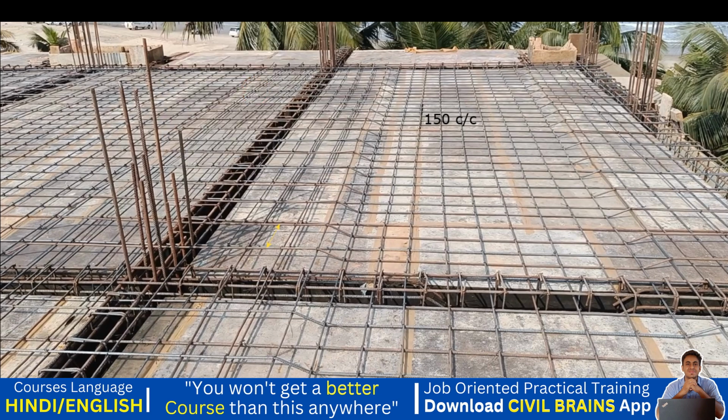You are getting my point? Similarly this is also 300, and here also it's the same thing. I wanted the spacing in the crank bar to be 150, but it has gone to 300, 300, 300. So in order to keep the spacing 150, we are going to give one more steel, which is called the top extra bar.